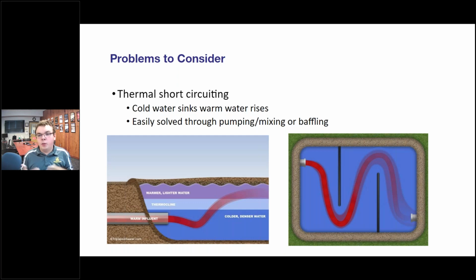But one thing to note is that even with baffling, there's that current forming that is the short circuit for your lagoon system, because the areas around that current where it isn't flowing as much are going to stay in that lagoon system for longer. So even with baffling, it's important to realize that you're only treating as well as your fastest particles through the lagoon system.